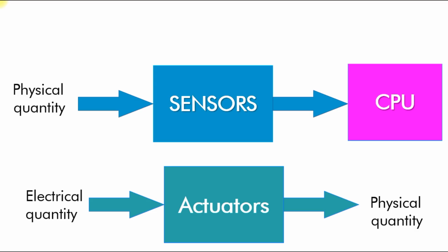Practically speaking, we are unable to give data directly to the DC motor. We need a driving mechanism in between them. Generally, the CPU just gives an on or off command to the driver circuit. The driver circuit takes the responsibility to control the fan, the DC motor.